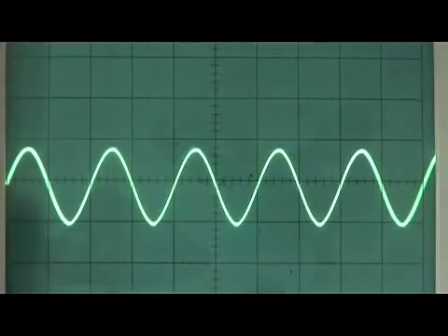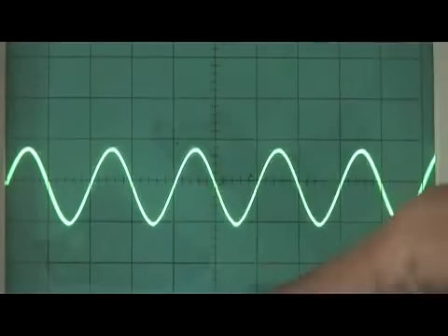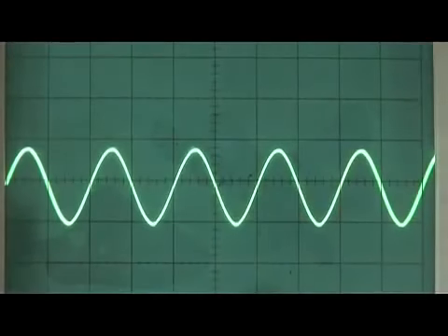So now we have to calculate the amplitude and the frequency of this signal using this CRO. Because the amplitude is always in the y direction, I can use this XY button, because I am interested only in the y direction. I am not interested in the x direction. When I press XY, it suppresses the x-axis, because I am only interested in my y-axis. You can see from here that it is properly coming from here to here.